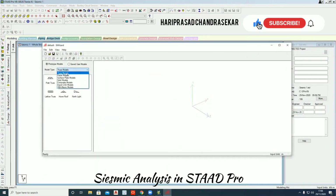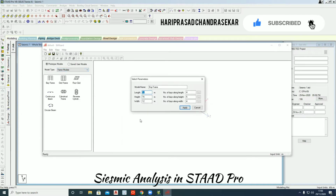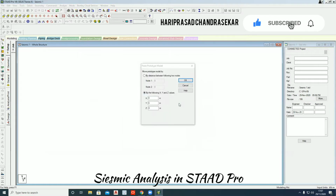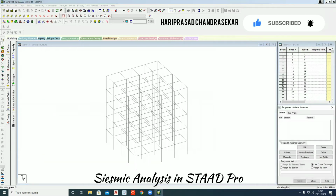And here I am going to use frame model. Just going to put this bay frame and I'm going to have the same length, height and width. I'm just going to put apply and then I'm going to close it. So it will ask the origin. Okay. And immediately after, we need to do support.